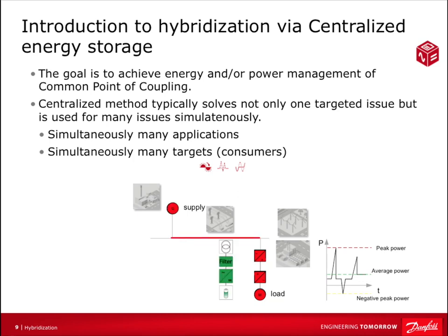So we would have here an additional energy storage where we could have potentially batteries, potentially some other form of energy storage, a DC to AC grid converter, and some filtering transformer that is going to feed into our grid supply. And this is going to allow us to compensate for those peak powers or even the negative power. There's going to be a point where we'll be able to absorb the excess energy and then store that power in our storage medium.